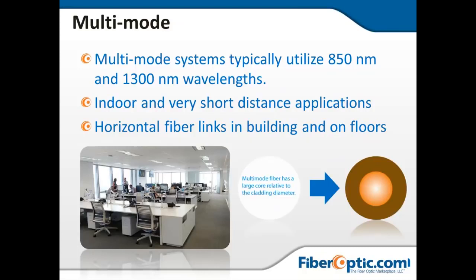So these are all accurate depictions of events that we would potentially see on an OTDR trace, but I think that there's always a few other things that could be added to here and are probably more indicative of what we would see if we were looking at a trace on a true OTDR versus just a graphical representation. So those are things to look at. And when we're talking about the OTDR and selecting it, the accuracy at which these OTDRs can read these reflective events and how much reflection is coming off these events is a huge factor.